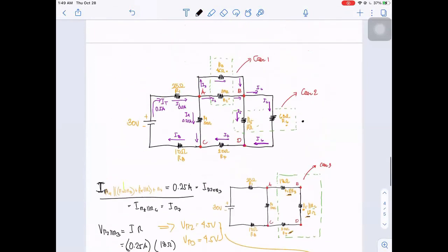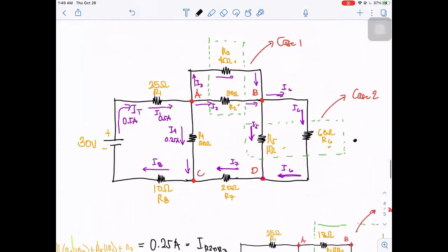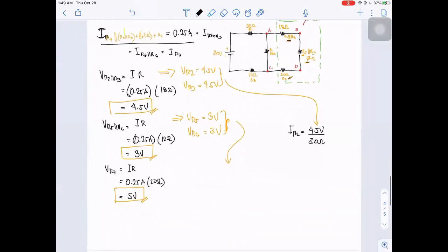So in our circuit, so this one, 30 ohms. And that is equivalent to 0.15 ampere. For IR3, we have 4.5 volts all over the 45 ohms resistance, and that is equivalent to 0.1 ampere.